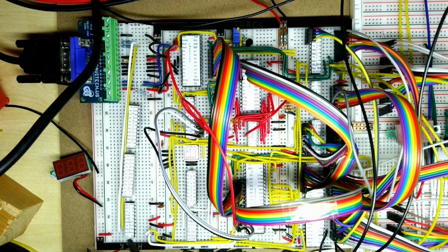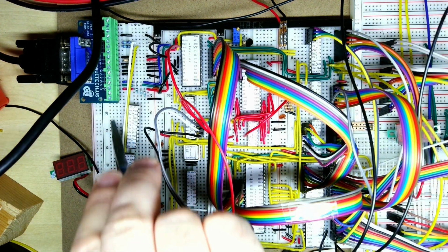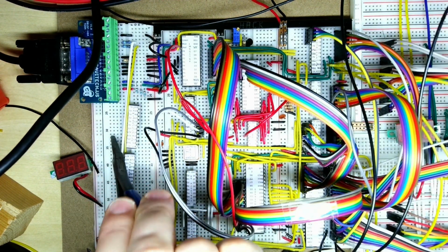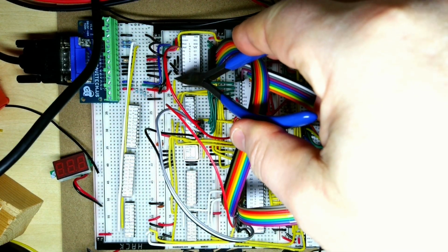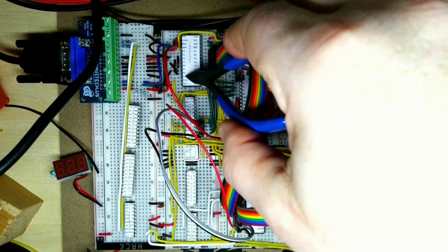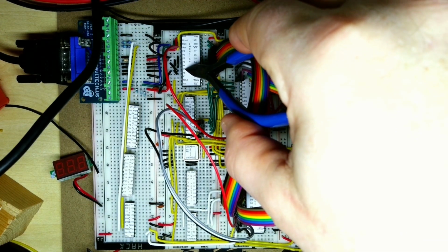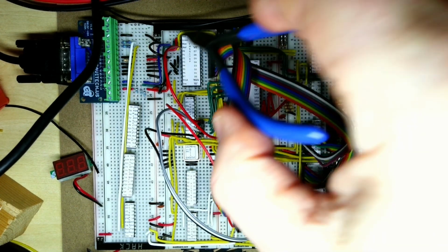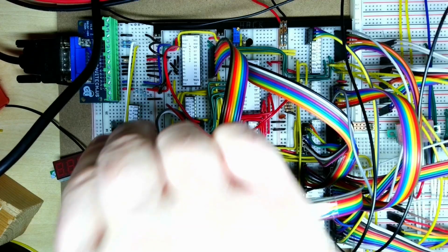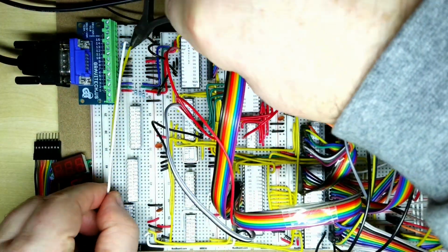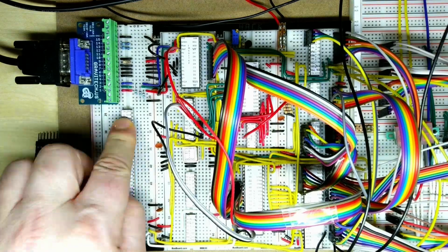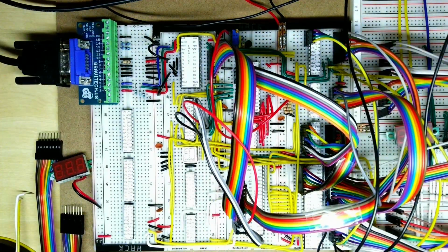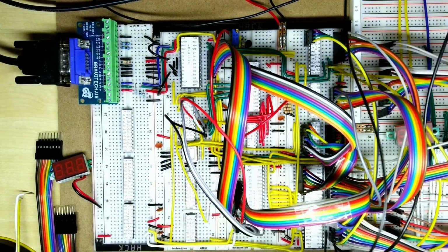Once we've wired it all up, then the output, P0 to P4, is going to be going from there over to the input to the video DAC, and we'll need to leave P7, P6 and P5 wired to 0, but the other lines are going to be connected to the output up here. So just remove the horizontal sync and vertical sync, plug in the chips. Now we're going to wire up the power and put decoupling capacitors in.